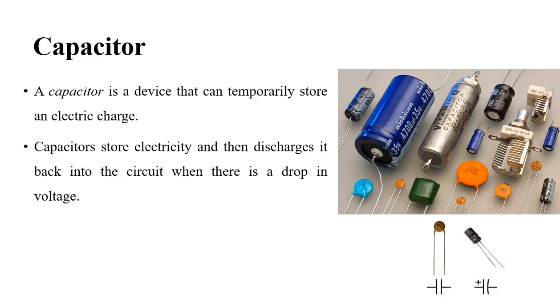In addition to this, it can be used for starting purposes, especially for components that need high energy. For example, compressors or motors need high energy. Some compressors actually need high energy during startup. In that case, the capacitor gives additional energy to the already existing power supply, so that the compressor will start automatically.